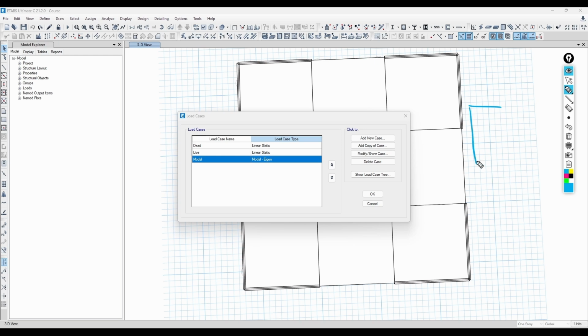Let's say this is my structure, and let's use a different color so it's more obvious, right? And these are the stories. So the first modal shape is the structure might go like this, right? And then this is the floor. And then for the second modal shape, the structure might go in the opposite direction, so it's going to be something like this, and then like this. So it just depends on the shape of the deformation of each floor, with the delta of each floor. We're going to get into that later on.